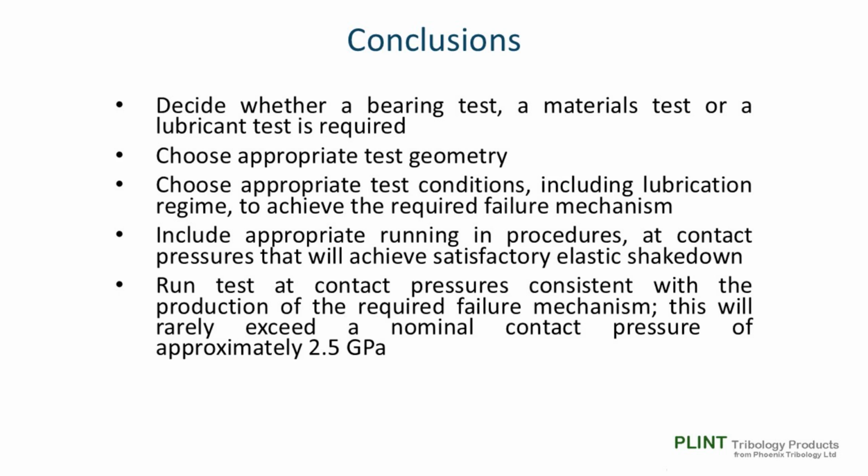Our test must include appropriate running-in procedures at contact pressures that will achieve satisfactory elastic shakedown. Subsequent test conditions must be at contact pressures consistent with the production of the required failure mechanism. This will rarely exceed a nominal contact pressure of approximately 2.5 gigapascals.